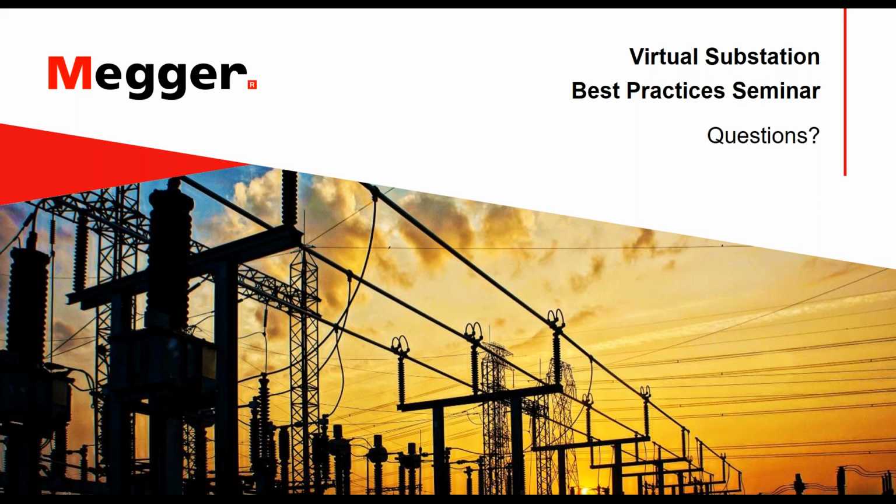So great question. If you look at IEEE standards, C57.12.00 or 12.90, the winding resistance and TTR tests are routine tests. What that means is that the test is applicable to all types of transformers. So even if it's a new design, or even if it's a new transformer, or even if there's field testing, these tests have to be performed or are recommended for all those scenarios.